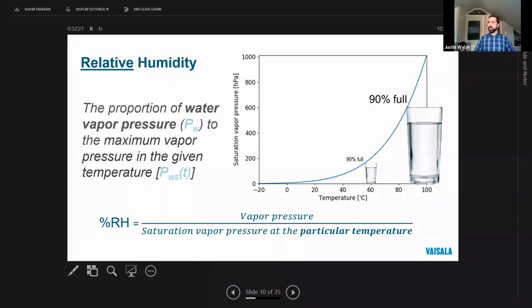So let's say we have a container or a room with 50% relative humidity in the middle at a temperature of 20 degrees C. We'll assume the humidity inside the room is evenly distributed, meaning the vapor pressure would be the same throughout the whole volume. Now, if we measured the relative humidity instead at the corner of the room where the sun is shining and the temperature is 1 degree higher, then we would only read a relative humidity of 47%. The wrong interpretation would be to assume that the room was drier in that corner, but it is only the relative humidity that is lower.